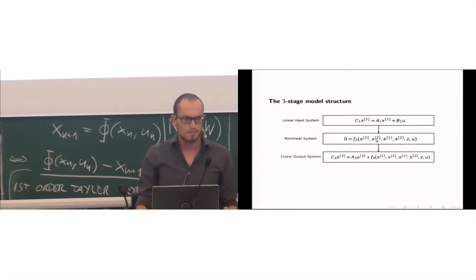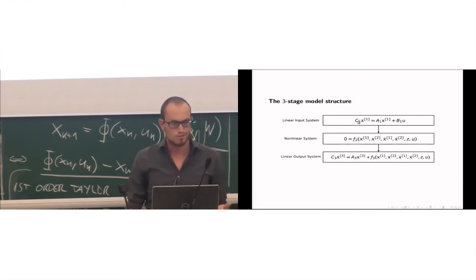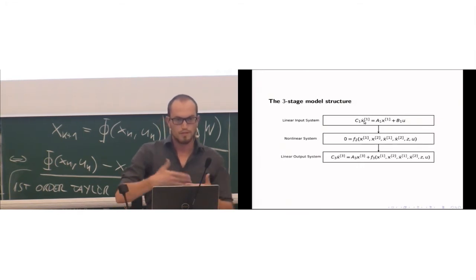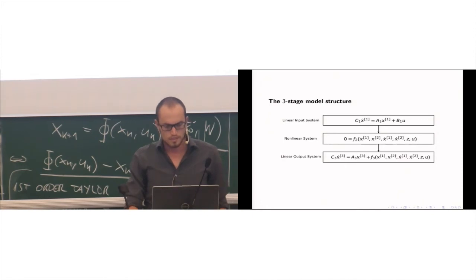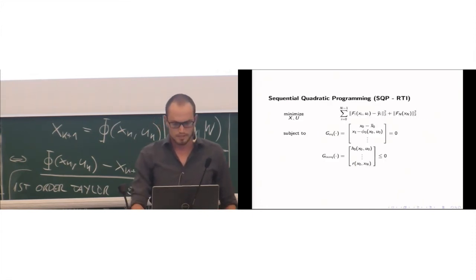But you might have other states that are defined by partially linear dynamics, which are obviously much more simple to treat. Sensitivities are constant, so you don't have to propagate sensitivities at all. If you apply an implicit method, you would not have to do Newton iterations for a linear system, of course. And the states are coupled, but only in one way: x2 has dynamics defined by x1, but not the other way around. So you just simulate one part of it and use the results to simulate the other part. It's kind of a one-way chain. This really sped up computations for certain applications.